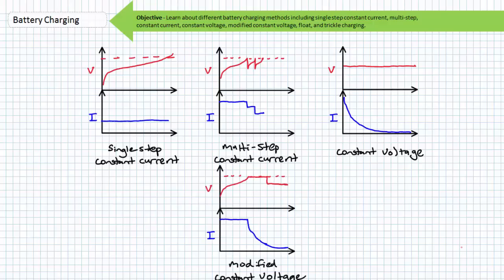One of the most common charging methods used for lead-acid chemistries is something called the modified constant voltage charging method, or the fast charge. Lead-acid batteries can't really be fast charged, so the term fast charge is somewhat of a misnomer. A complete charge takes a long time, and anything faster is a compromise. Lead-acid batteries can, however, be charged to around 70 or 80% relatively quickly. The all-important saturation charge takes up the remaining time. A partial charge is fine, provided the lead-acid battery occasionally receives a fully saturated charge to prevent sulfation.